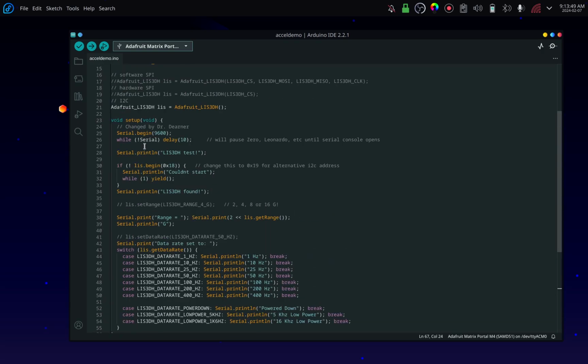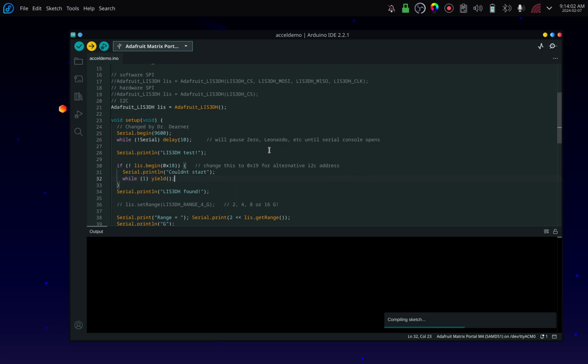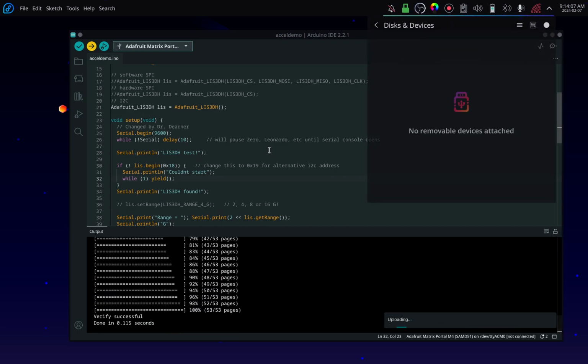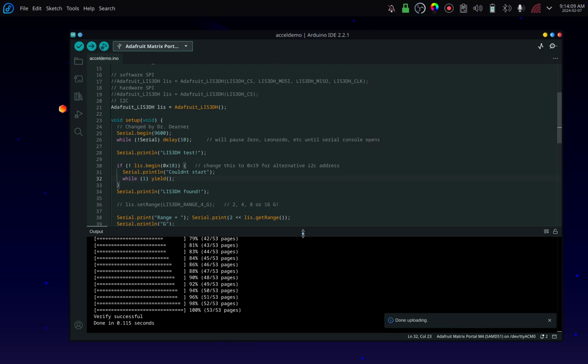So I want you to make this one change to your serial.begin, and then I want you to upload this code to your board. So watch me and then do this and verify that you get the same results. I'm going to hit Control U to upload to my board. I've already got it plugged in. It's going to compile it and upload it. I get this little drop-down menu because it thinks it's a disk drive. And then I'm going to open up my serial monitor.